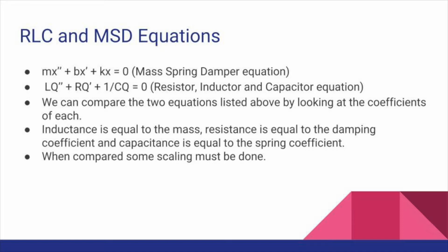The mass coefficient from the MSD equation can be resembled in the RLC equation with the inductance. Same goes for the damping coefficient versus the resistance and the spring constant versus the 1 over capacitance. When trying to model an MSD system with electrical components, scaling must be considered. The zeta should not change dramatically when scaling up or down.